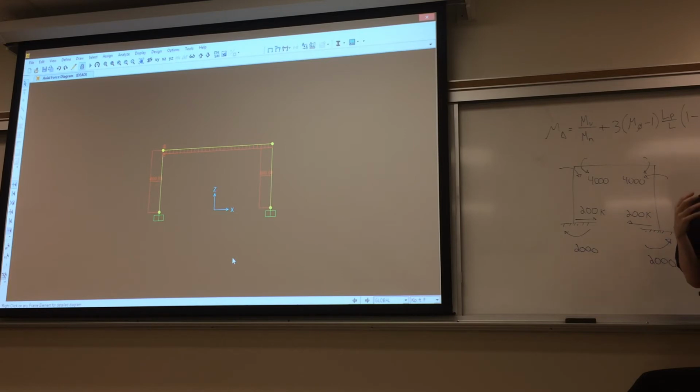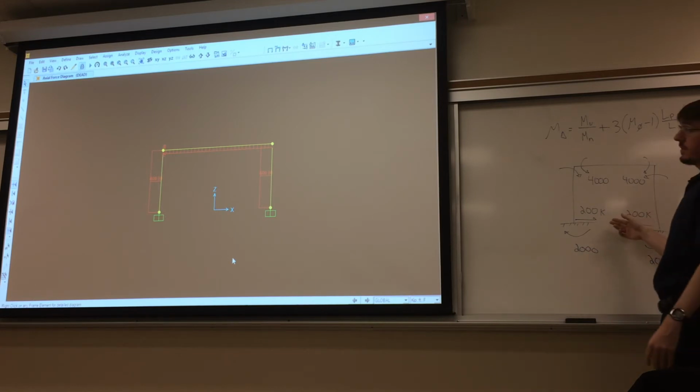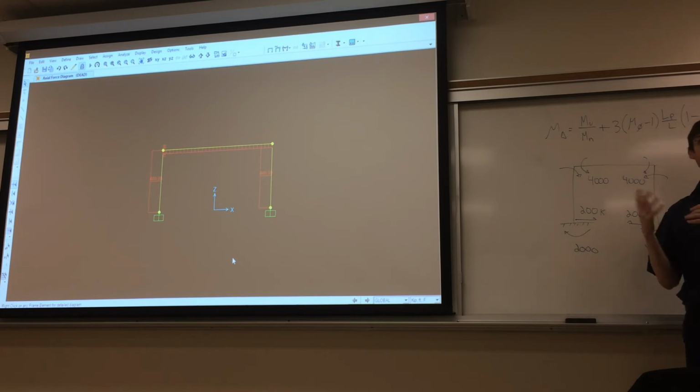So generally speaking, if you're trying to, let's say, tune a model and you're starting out simple and make sure your computer model is doing what you want it to do, you have flexure analysis as kind of one of your go-to hand calculations. So you could check your flexural analysis by hand with your computer program. You can make sure that key components are working beforehand. And then you can go in and add more complexity. Then you can start worrying about shear deformations and axial deformations.